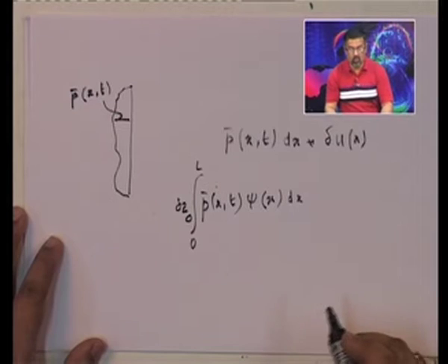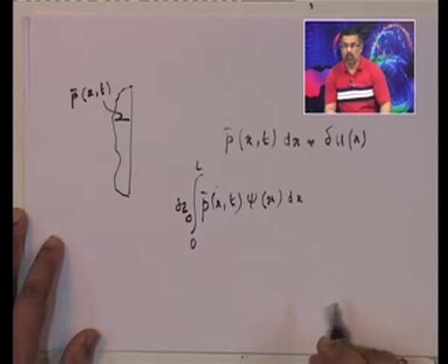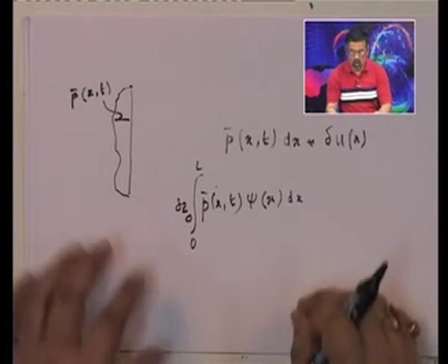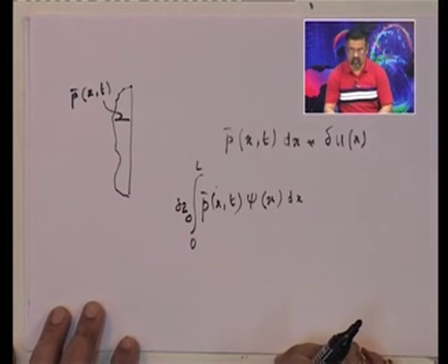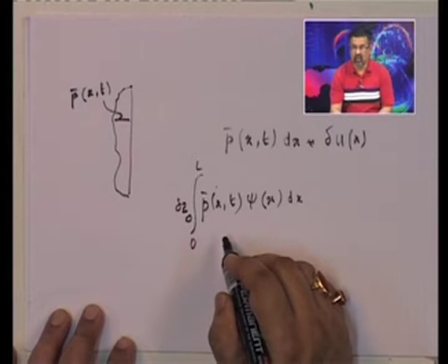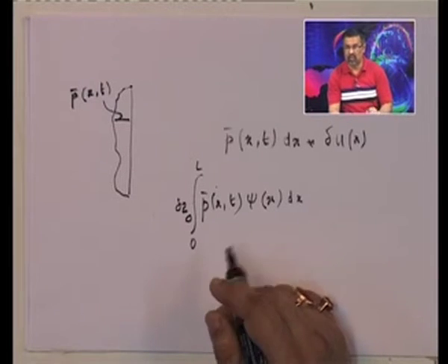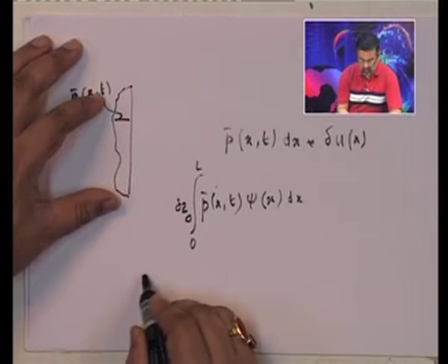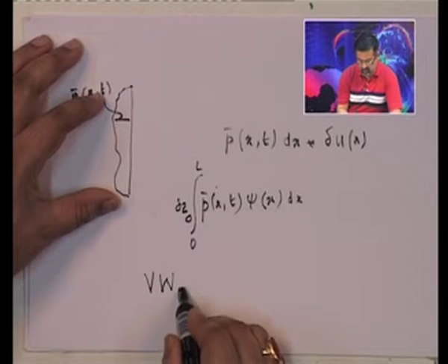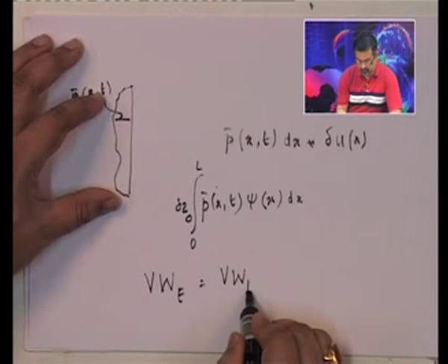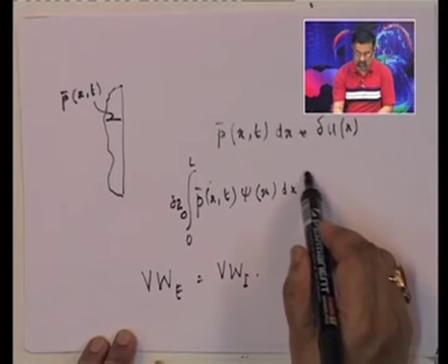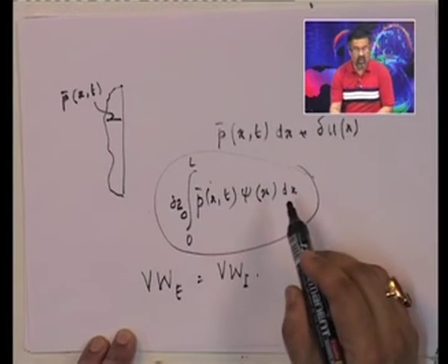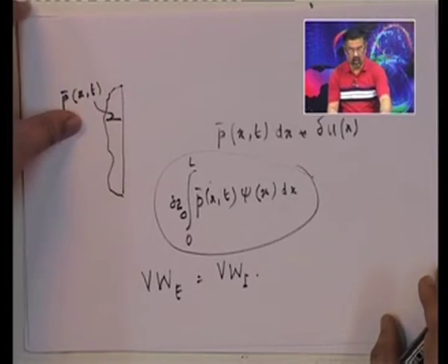Okay. So, now the question becomes that, look, the work done by your external forces is always positive, and the work done by the internal forces is always negative, so that is why this one actually becomes something like this. Okay. So, the external forces are these, and the internal forces is the work done by elastic forces, which is the bending moment, and the work done by the inertial forces. So, putting all of those down, I get this.